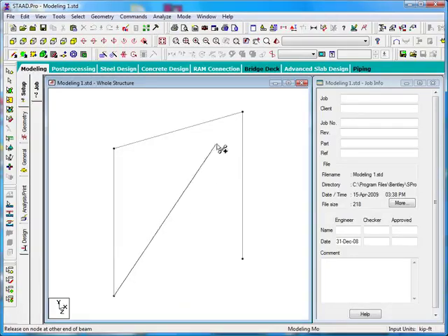and notice that I'm rubber banding from that point. So this beam that I'm drawing just snapped to that node, and I'll come up to the opposite corner and again get reasonably close to the node and click once and move away, and I can see that I've left a single beam. If I wanted to draw the second beam, I could click at the upper left hand corner and stretch down and click near the lower right hand corner, and now I've recreated those two diagonals.